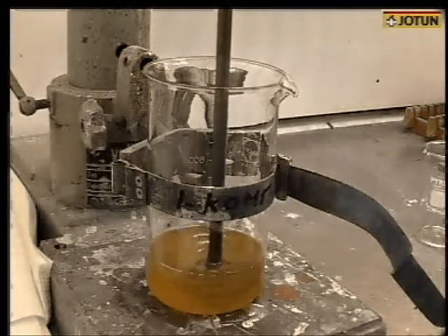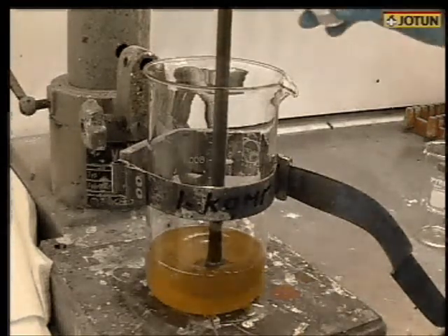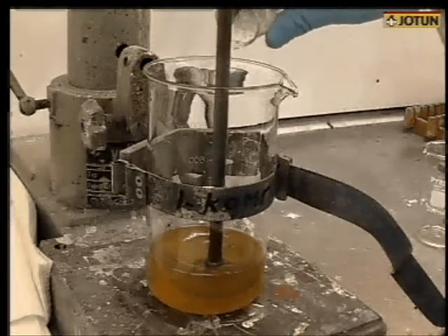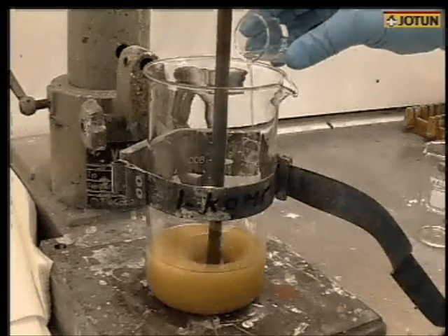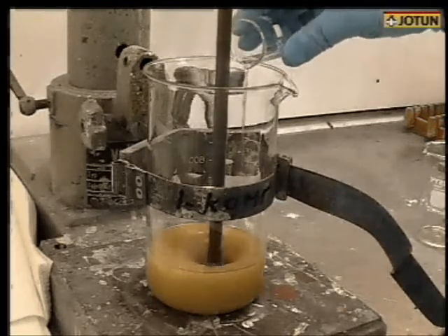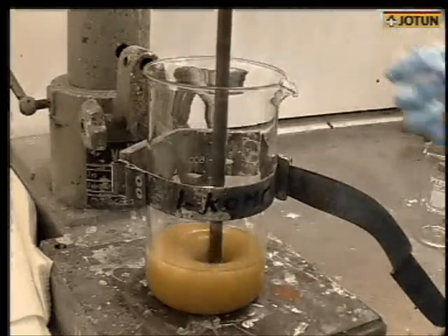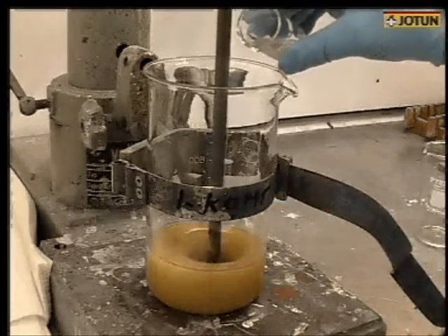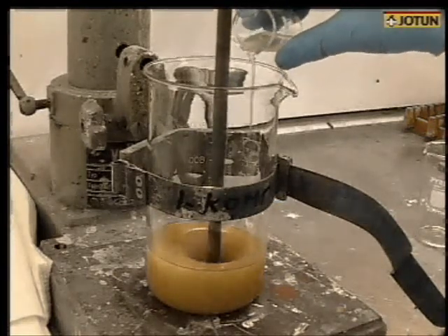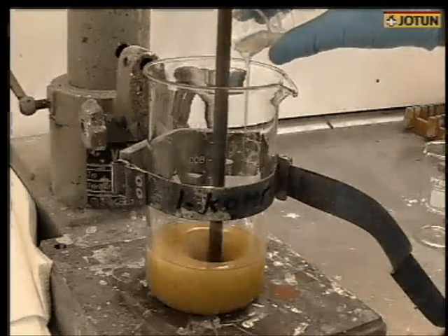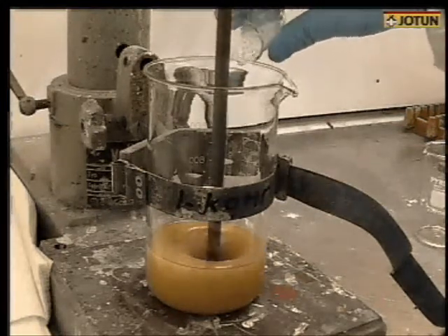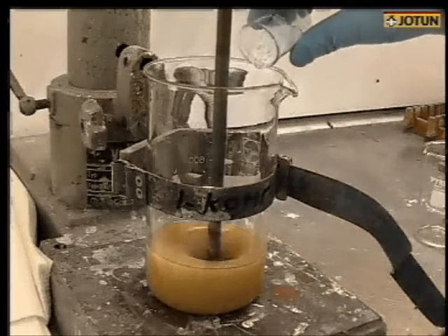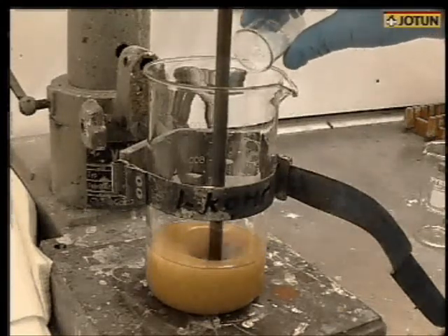The next step is to include certain raw materials to a proportion of the concentrated mixture, such as additives, which are important for dispersion and anti-settling of the pigments. Usually, they are added under high-speed agitation to ensure an even distribution of them in the vehicle. Extenders are added to reinforce the paint film and to give the paint the correct gloss and consistency to make it suitable for spraying, rolling and brushing.